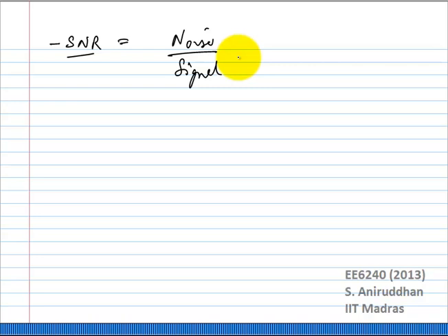What is the noise power? We'll have to integrate the area under these noise curves, or rather we will have to specify maybe a spot SNR or a spot phase noise. Okay. And compare it to your signal power at F0. That is normally the way to characterize phase noise. Now, having known so much, knowing that phase noise is characterized as noise to signal ratio, can you tell me if the NMOS cross coupled pair will be better or the PMOS cross or the complementary VCO will be better, and why?